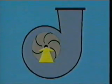Gas enters the compressor through the suction port and is directed to the center of the impeller. As the impeller rotates, the gas rotates with it. This circular motion generates the forces that lift and move the gas away from the center of the impeller, as well as creating a suction at the center of the impeller. Because the outside edge of the impeller travels faster than the center of the impeller, the gas is forced to increase its speed as it moves outward. The two forces, the lifting force and the centrifugal force, increase the motion energy or kinetic energy of the gas.